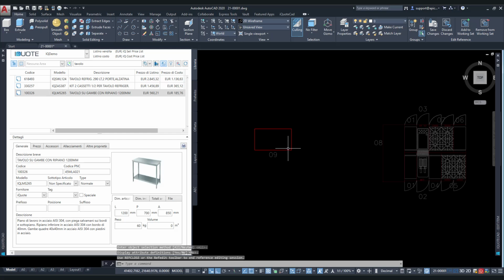This means that whatever changes we make now are not applied to the original block, but rather to the copy. The software also automatically enters AutoCAD's block editor mode, graying out the rest of the drawing, which at this point is not editable. The only editable part is the block itself, which is no longer treated as a block but has been temporarily exploded into its constituent elements.